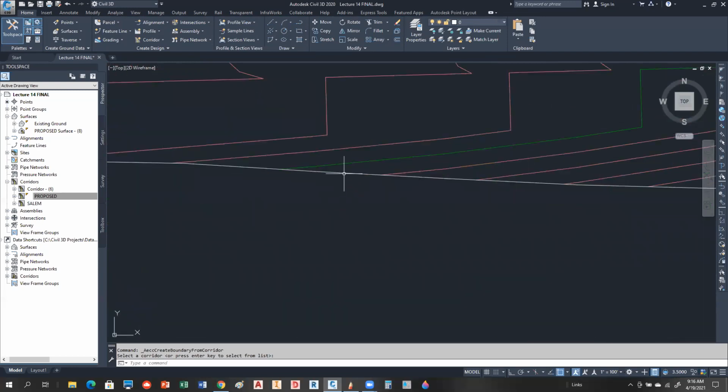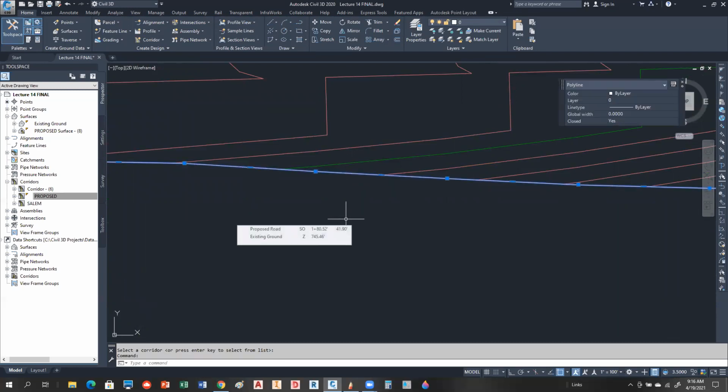Yeah. So this is a 2D polyline, and it puts it on the 0 elevation, or 0 layer, excuse me. So if you want that thing to be hidden, what you can do is probably freeze it, but you might want to put it on a layer that's just hidden out of the way. So you might want to generate a layer for that.